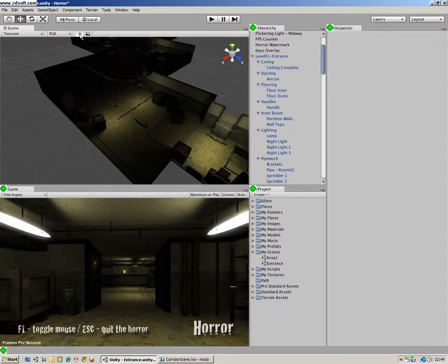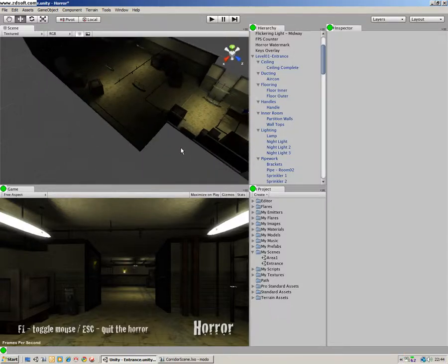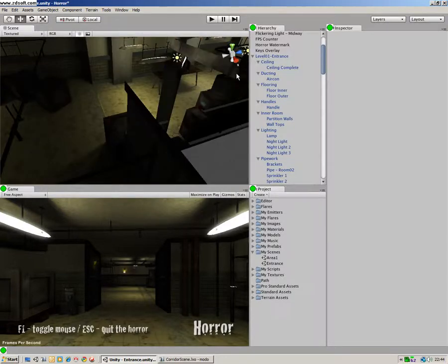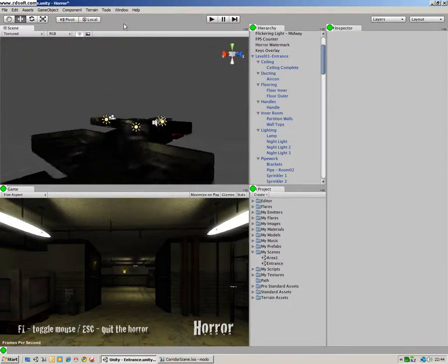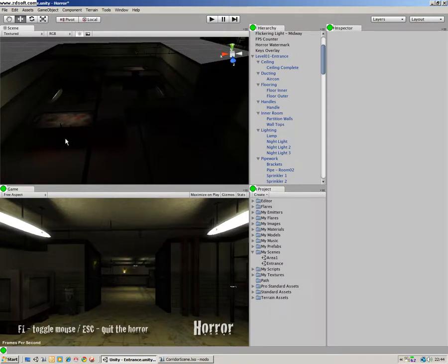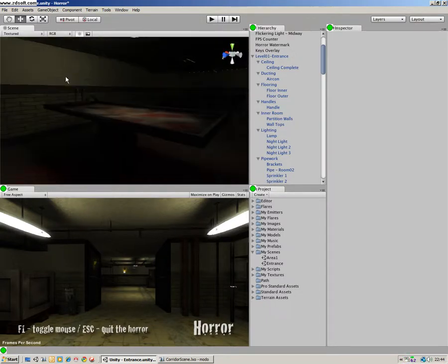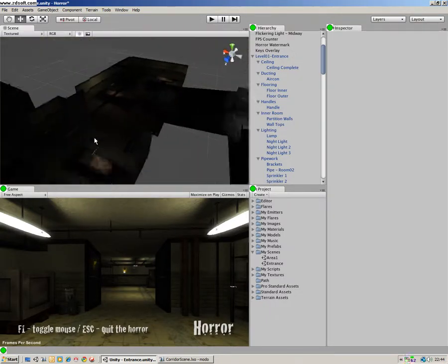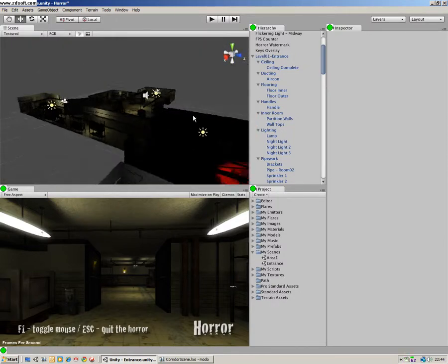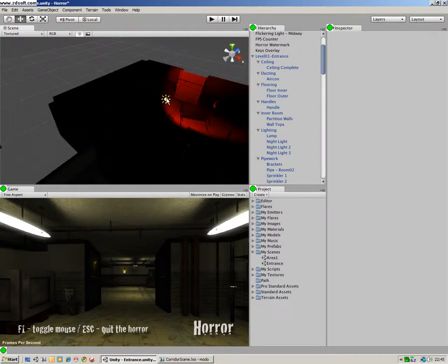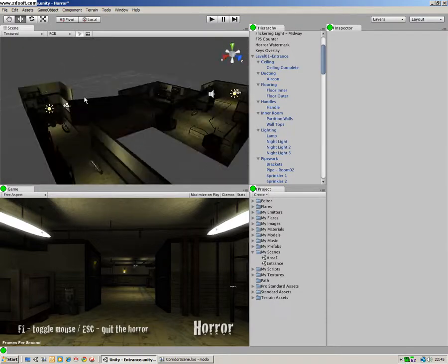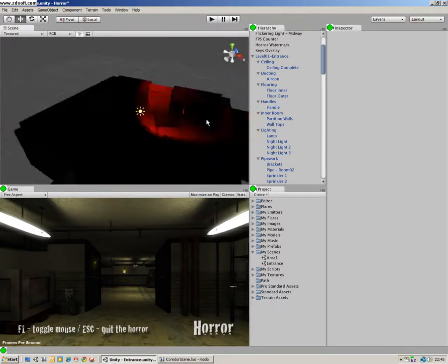So if I turn the lighting on, you'll see that the shadows are nice soft shadows, and they're being cast by however many lights is needed. And all this is made within Modo, and we generate light maps to map these areas. And then within Unity we can save the CPU power and the graphics card power for doing some nice effects. So where you see this little light symbol, that is actually a dynamic real-time light, but I'm only using them within Unity for special effects, like here.